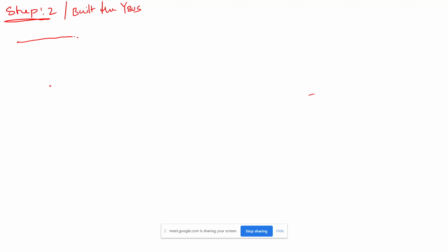This is from 1 to 2, this is bus 1, this is 2, and this is 3. We know the value of this is j10 in admittance. Just now we found that value, it is minus j5, and this is j4. So these are all the admittance values. From this I need to find the Y bus.